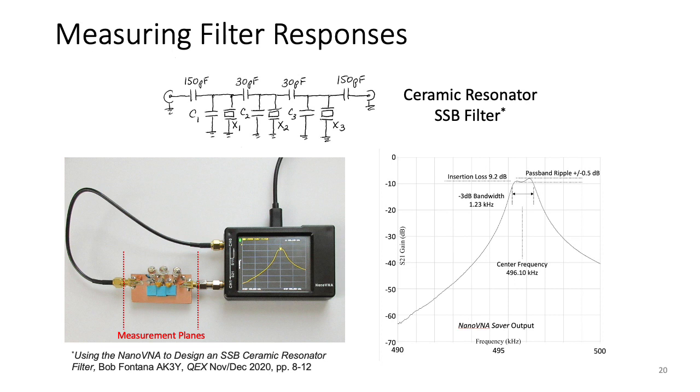The thing to take into account here is that I want to eliminate the effects of the coaxial cables and connectors attached to my filter. And so I set up the measurement planes in such a fashion that my short, open, and load through calibration runs are done at these 2 points. So for example, I will apply the short, open, and load at this location here, and then I will connect the one cable to this barrel. I'll connect this together here, and this will be my through run. In other words, bypassing the filter itself.